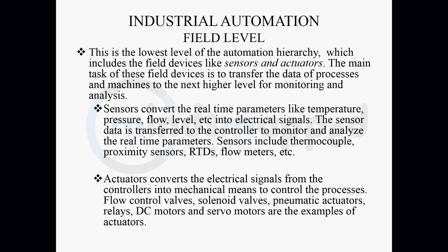Let's say if it's a barcode scanner, it's constantly going to be sensing for a barcode. As soon as the box comes in its vicinity and it can scan the barcode on it, it will scan the barcode, gather the information, and pass on the same information to the controller.